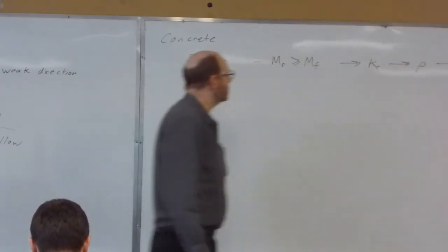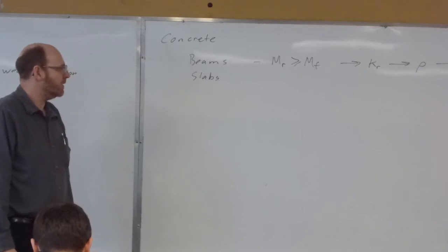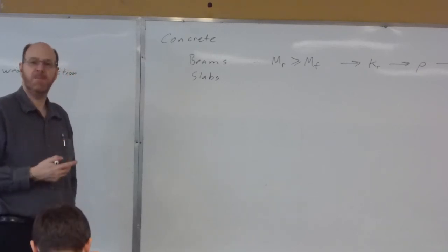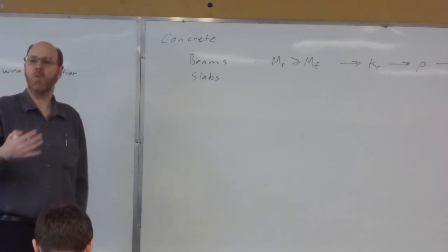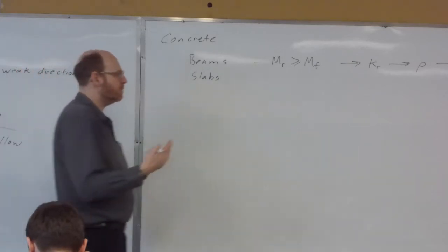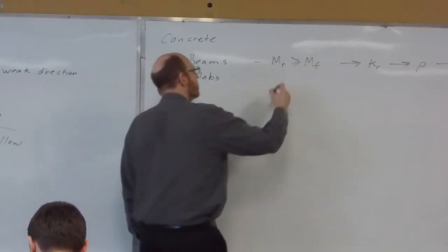Now our slabs, for the most part, follow the same principle. The difference is instead of putting a finite number of bars, the bar is done in terms of spacing over a 1 meter wide strip. Right? So we do spacing instead of a finite number of bars. We also had our shear resistance.